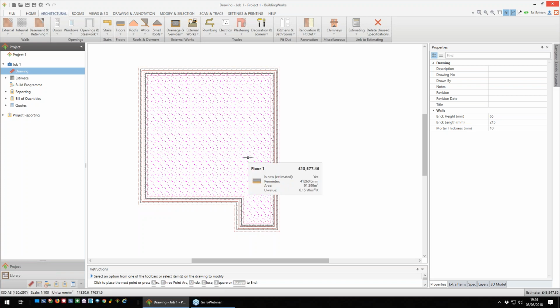Okay, now the reason I did that before the walls is that if I put my internal walls in, I would have to repeat that process because it would actually do a slab within each room. I'm cheating, and this will ever so slightly overestimate because there are going to be certain areas where the walls are and there's blockwork. If you want to be super precise, you can do your walls first, then do the slab in each room individually.